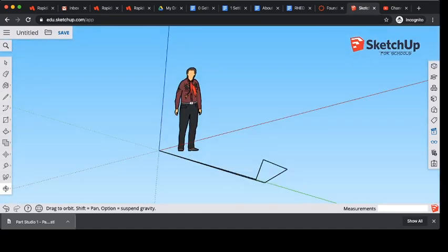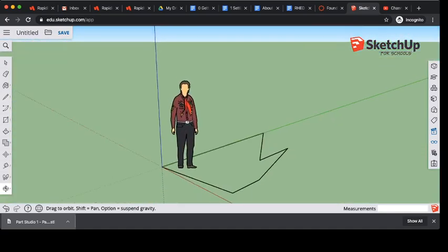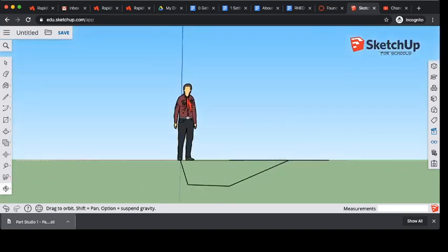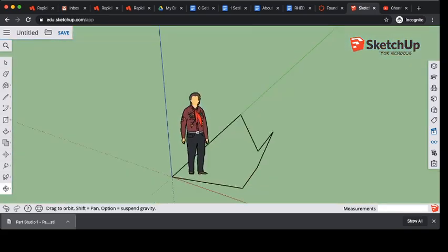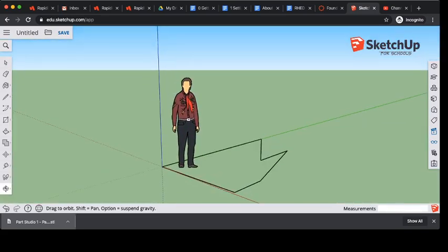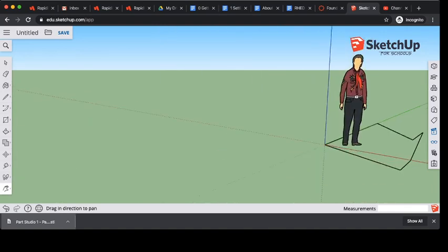Now, orbiting around, changing the view. It's kind of hard to see sometimes because this is a two-dimensional representation of something that is inherently 3D. This little option down here at the bottom will let you change the view. So an orbit, if you click, will let you rotate around. And you can see I got a bunch of random lines there. Not particularly useful, but whatever. Some of the other visualization tools: the little hand is called a pan. If you click, it'll grab the screen and move it around without rotating.